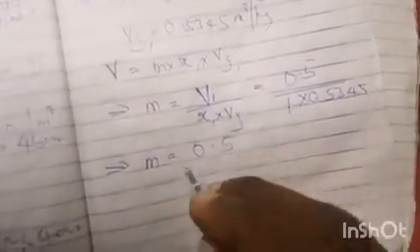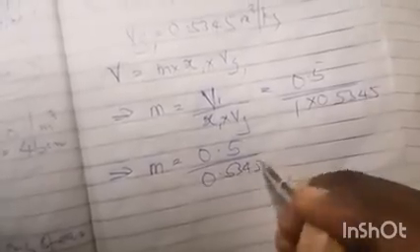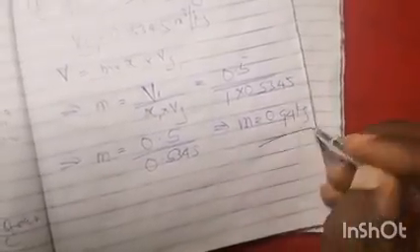Remember, the initial volume was given to us, that's the volume at state 1, given as 0.5. So you simply have 0.5 divided by the dryness fraction, which is 1 since it is superheated, times VG1, which is 0.5345. So mass is equal to 0.5 divided by 0.5345, which implies that the mass is 0.94 kg. That gives us the mass of the steam.